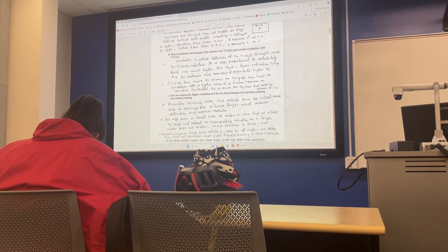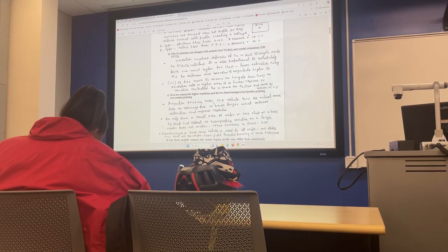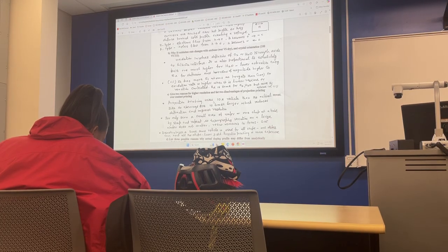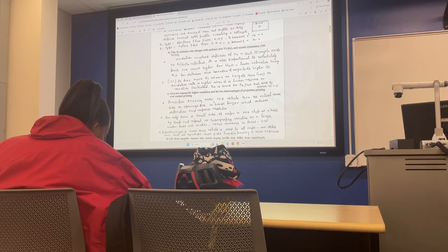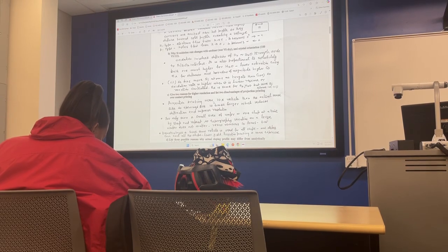The second is you don't expose the whole wafer. You are exposing one chip at a time, so you are scanning. It's a scan, step and repeat. When you are looking at a very tiny area, there is a variation in the wafer topology. Since you are exposing a tiny area at a time, chances are you don't have huge roughness variation.